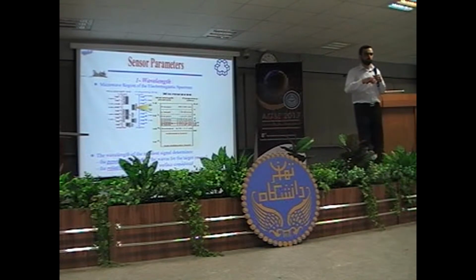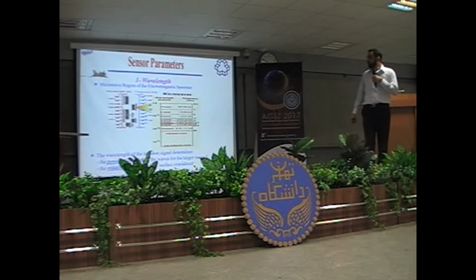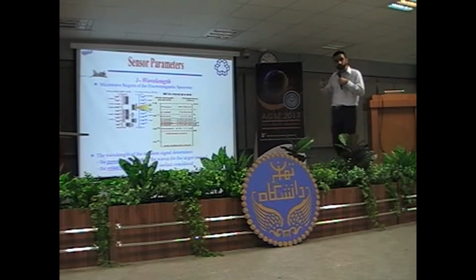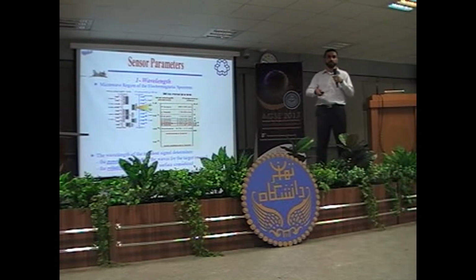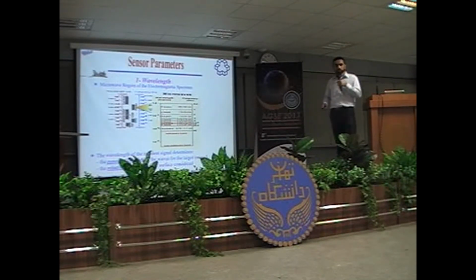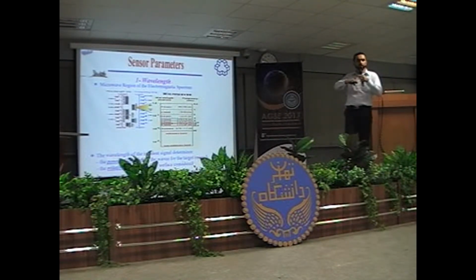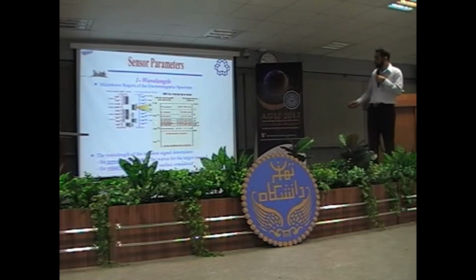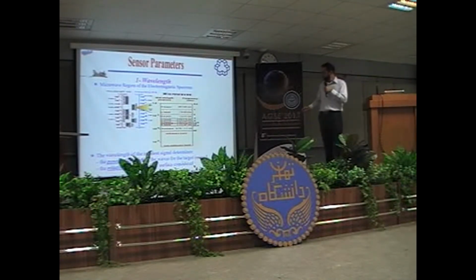If you want to go, for example, in forest application, we are usually interested in higher penetration through the canopy in order to have information from the bottom, from the tree, from the trunk. So if penetration is very important for you in the application, then you should go for L-band, higher wavelengths. If, for example, penetration is not that important, for example in urban areas, you can use X-band images, or for vegetation area, agriculture application, the C-band works very well. So what kind of image to select really depends on the application that you're going to follow.